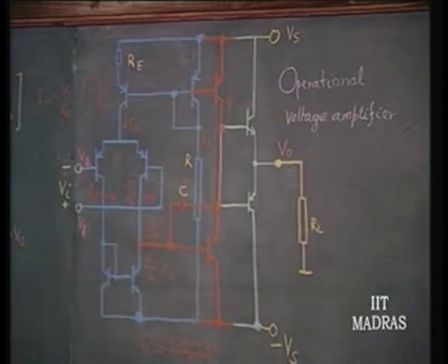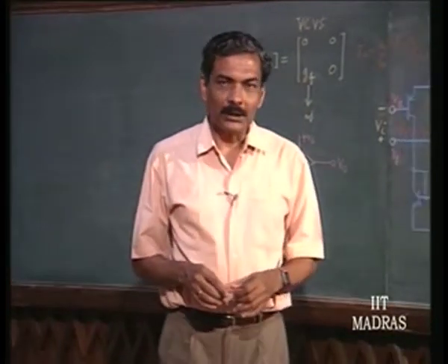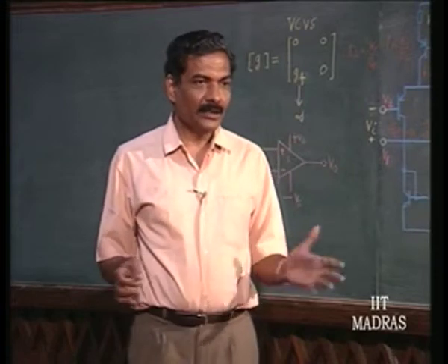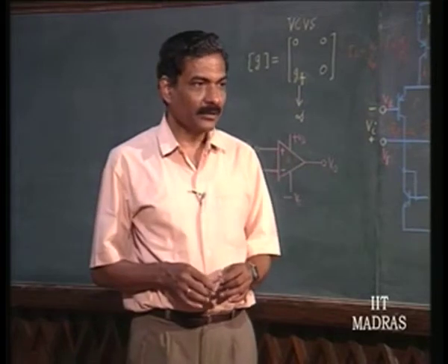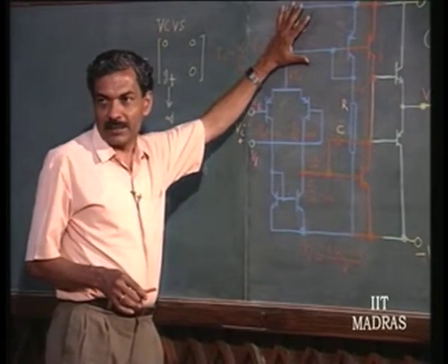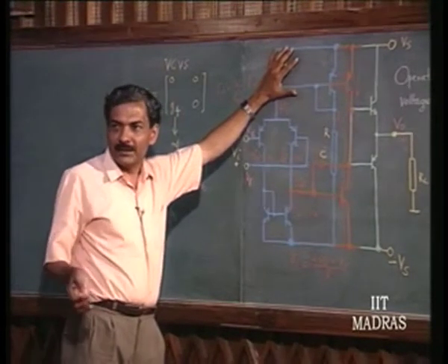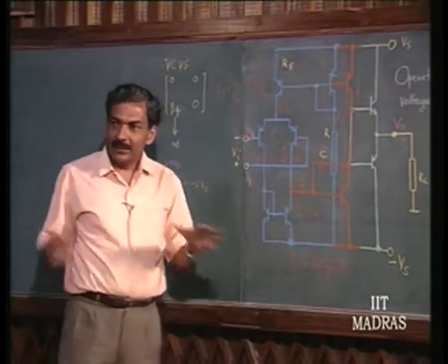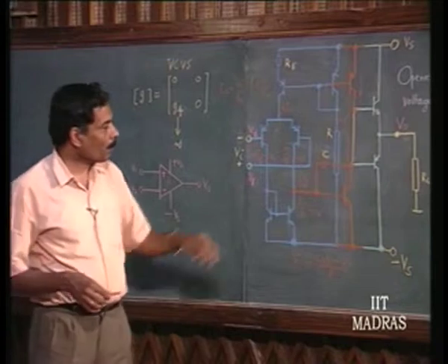So, you can straight away see that it has the maximum common mode signal swing desired, so as to prevent any what? Why do you want this kind of common mode swing? Latch up problem when you use it again in negative feedback situation. So, this stage has been therefore well chosen, and that is why very few changes have taken place over the years, as to the topology of the configuration that is going to act as input stage.